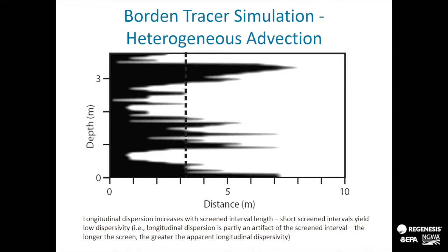And so we're seeing a 4 order of magnitude variation of velocities, and this is where they actually measured the permeability in the lab on samples that were collected at 5 centimeter intervals. The geologist is saying it's just a sandbox, but the lab is telling us something very different. So this is a simulated tracer study showing the variation in velocities that are going to occur in this sandbox.